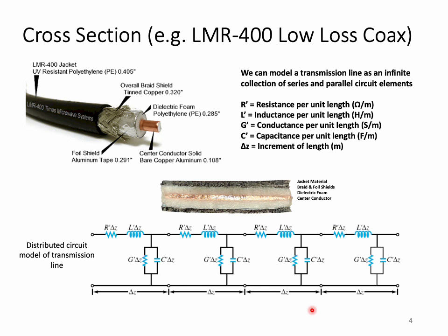In 1855, about 3 years before that first transatlantic cable was completed, Professor William Thomson, later known as Lord Kelvin, predicted the poor performance of the 1858 transatlantic submarine cable by formulating a diffusion model for a transmission line consisting of distributed resistance and capacitive elements. About 26 years later, in 1884, the concept of inductance was finally quantified by Oliver Heaviside, and this led him to the more accurate model for a transmission line that we see here.